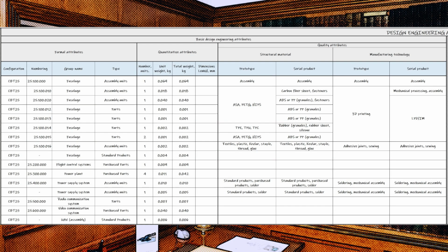The second functional model of the BOM is the BOM design engineering attributes model, which is the responsibility of the design engineer. According to criteria 12, 13, and 14, the conditions are met. The upper and middle level components are listed in the product structure in separate positions, while the low level components are not listed separately but as one generalizing combined position in the structure, called fasteners and components and connectors accordingly.